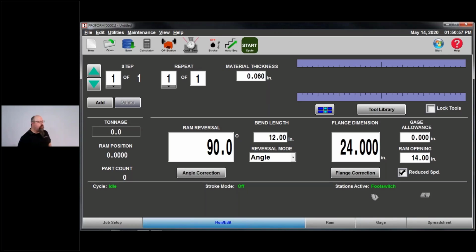Cool. So with the majority of you being engineers, that's not surprising. This is what the offline software is designed for, to allow me to pull a part out of whatever design software, Solid Edge, SolidWorks, Pro E, whatever it is you're using, to take those drawings into a DXF, DWG, or IGES file and bring them directly into the offline software. And then in the offline software, I create a program. That program can go directly out to the machine, and it's going to already have a majority of the programming finished. So that makes sense.